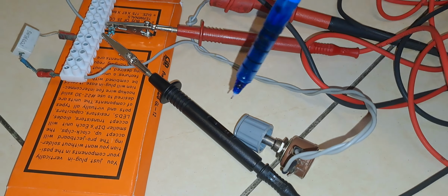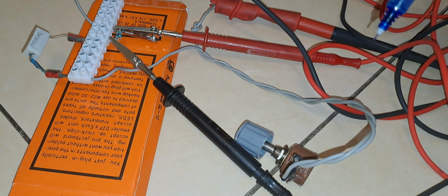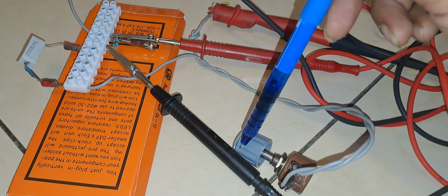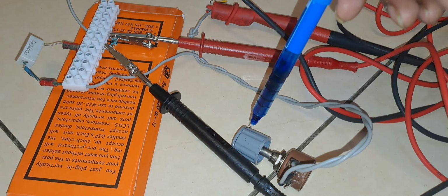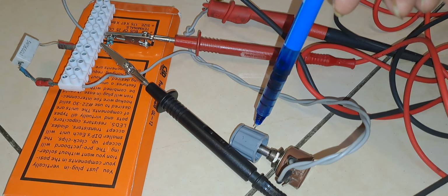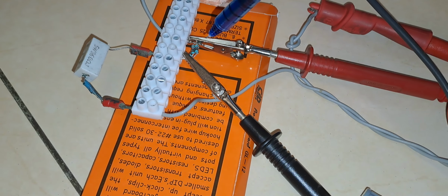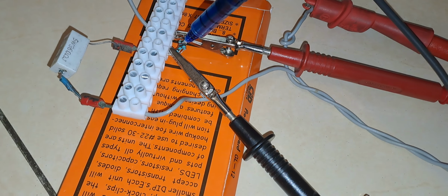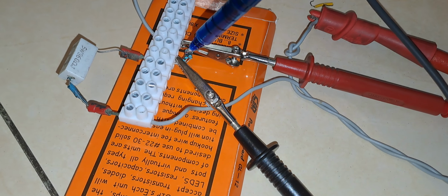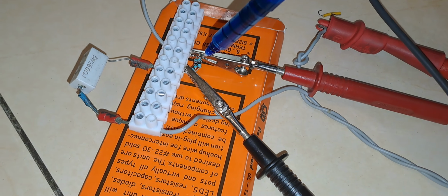This kind of 4 to 20 milliampere current simulator or current source is used in industrial applications to control currents in analog input channels. As you can see here, this potentiometer is responsible for controlling the current. As I control the current between 4 and 20 milliamps, the same current will be flowing via this resistor to the power supply. So there will be a voltage drop of 1 to 5 volts. This voltage drop of 1 to 5 volts across this resistor corresponds to 4 to 20 milliampere of the current.